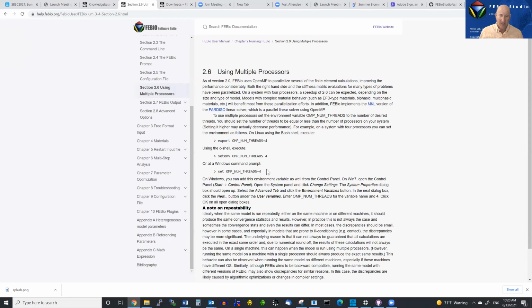So iterative solvers can be an option for certain classes of problems that allow you to expand the size of models you can effectively solve with FEBio into the millions of nodes and elements. But the drawback is that, generally speaking, they work very poorly with problems that involve contact, or any situation that produces the relatively stiff or poorly conditioned stiffness matrices characteristic of solid structural mechanics. I'll stop there. Let's go back to the questions.